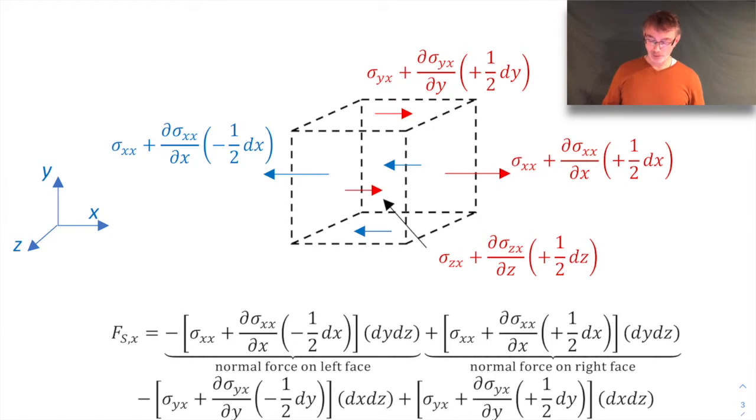And then we have corresponding stresses on what we call the negative faces. The negative faces are ones that have normal vectors pointing in the negative direction. So this would be on a negative face back here because the outward pointing normal on that face points in the minus x direction. And the stress on that would also be a sigma xx. Same sort of thing with down here. This would be a sigma yx and a sigma zx. Okay, so anyway, that's the stress sign convention.